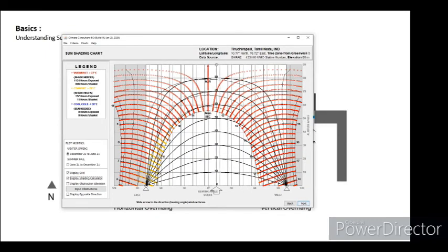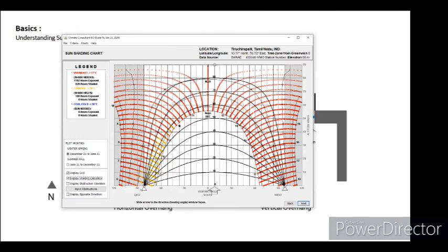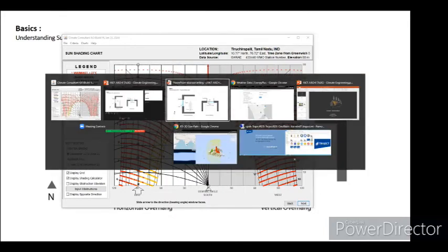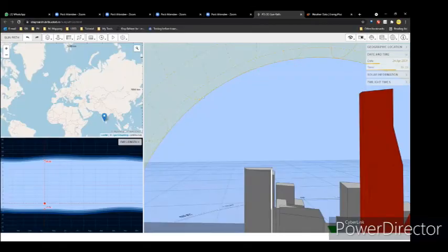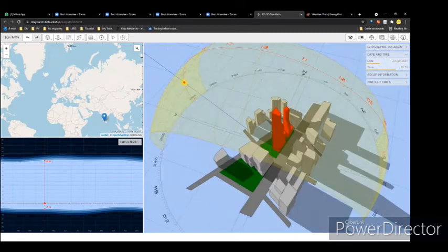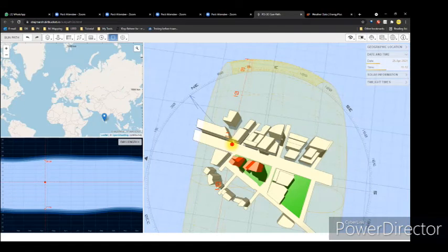And similarly, you can move this chart. Let's say I'm putting it on the west side of the window and see what should be the angle of the windows. And you go to the east and measure the angle. So if you see in the sun path, the sun is probably from the east, I guess. Yes, sun from the east needs the shading system probably on the west side or similarly. So the east and west require one vertical fin on opposite directions with the horizontal shading.